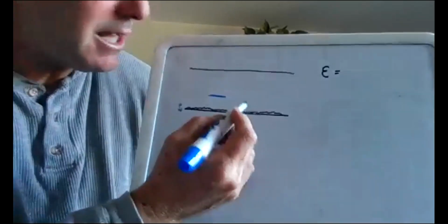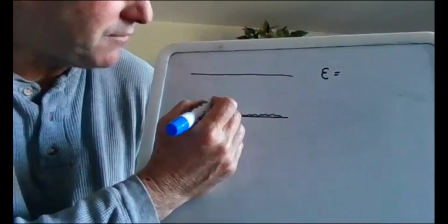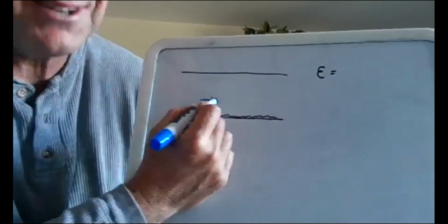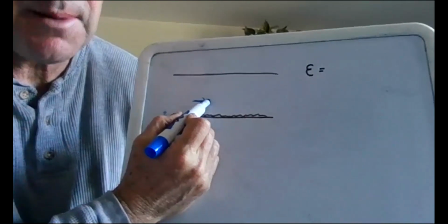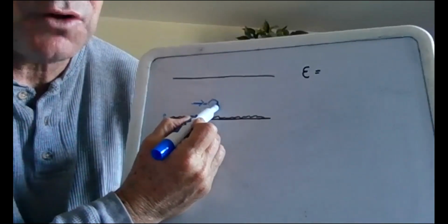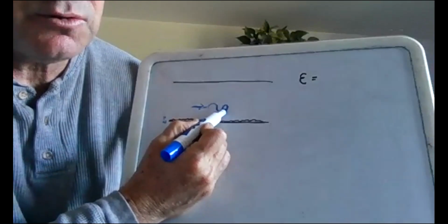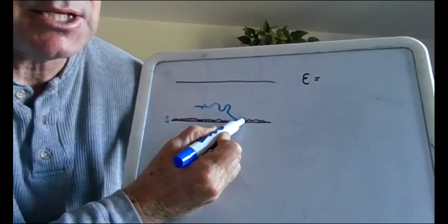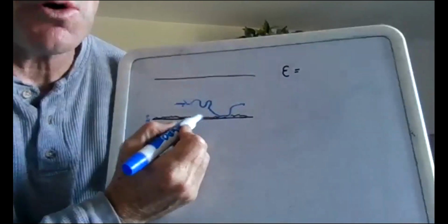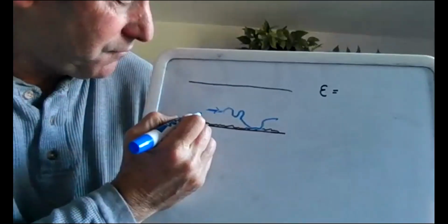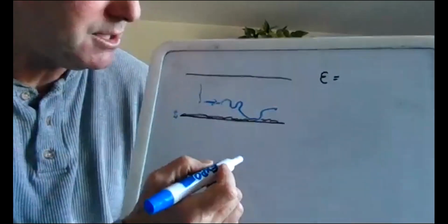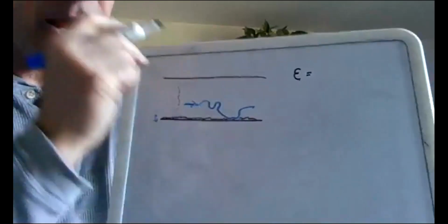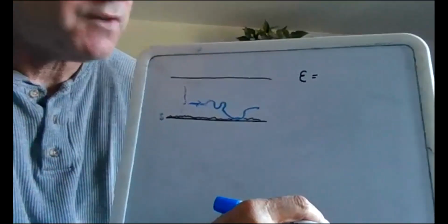Hey, what difference does it make? Well, for turbulent flow, it makes a huge difference, because you remember, any bit of fluid ends up having a variation in its flow up and down, and that can include down basically into that rough area and up. And so any particle of fluid that's not following the no-slip condition is actually going to penetrate into that area like that, and we're going to end up getting some frictional effects according to it.